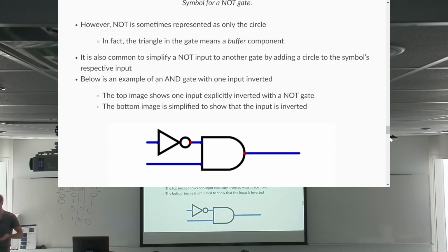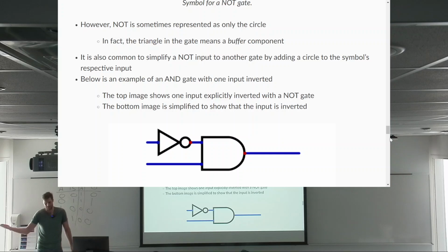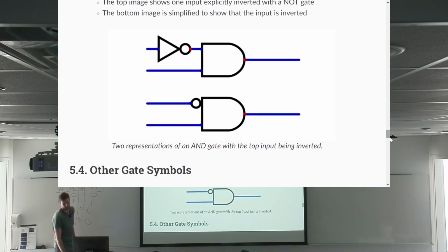We can also go the other way where I give you a truth table and say, build a circuit that does this. Anyways, because it's common to want to invert an input right before you put it into some gate, it's common to draw it like that. Depending on the design, I may or may not do that, but this is a common thing to see. This means not A and B. We're inverting the input right before going into the gate, just as a shorthand. Cool? Cool.